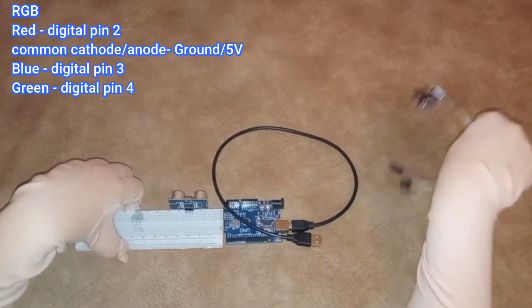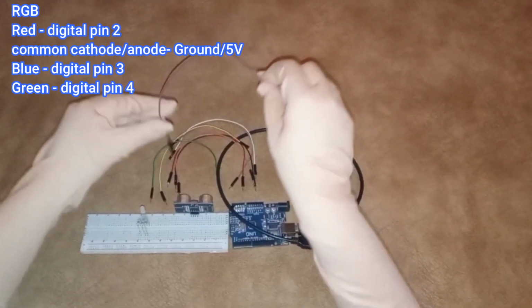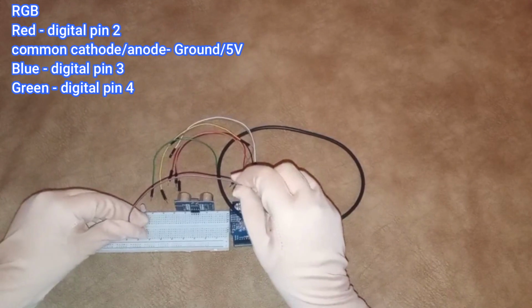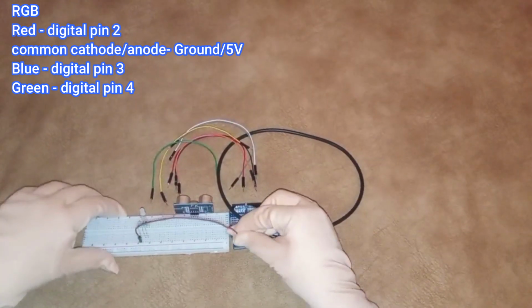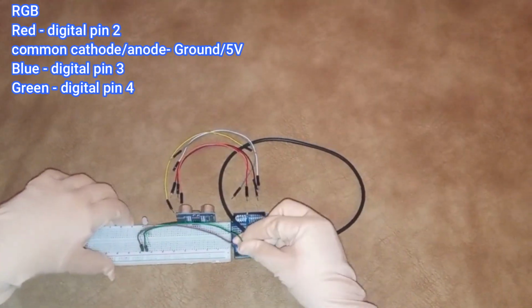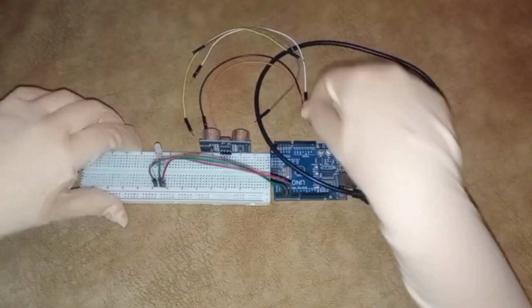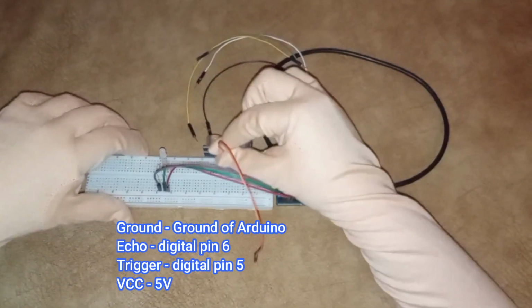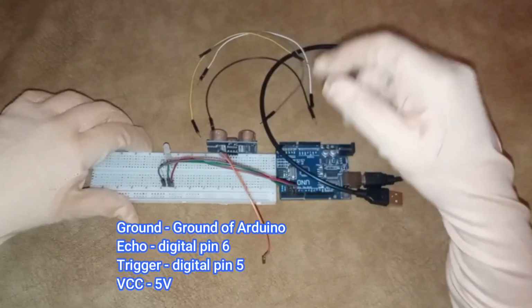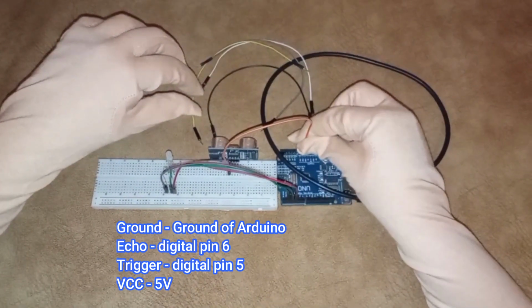Now we'll make the jumper wire connections with the Arduino. I'm connecting the red positive terminal to 2, blue positive terminal to 3 and green positive terminal to 4. Now I am connecting the ground of the ultrasonic sensor to the ground of the Arduino, the echo pin to pin number 6, trigger pin to pin number 5.